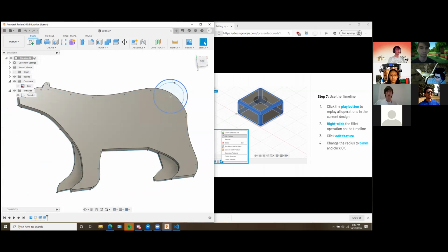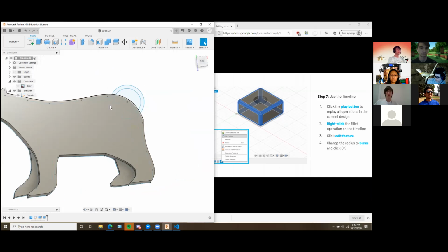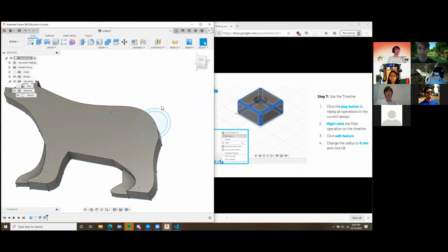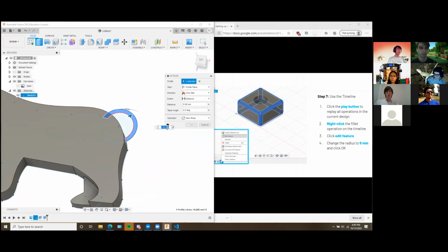And although I don't have it here yet, I can. So let's say you wanted to create a new extrude for the keychain. You could do it separately. So I could just click the extrude button and do the same height. So let's say I do 5.